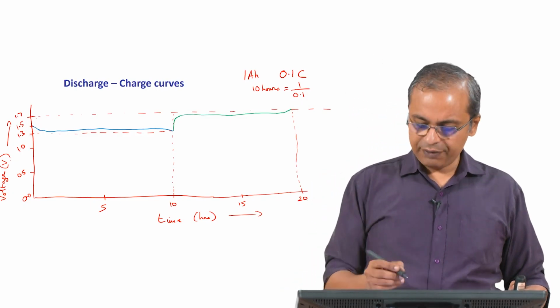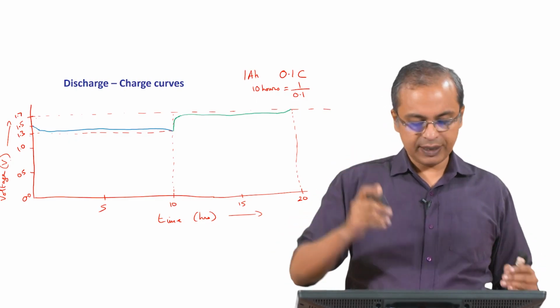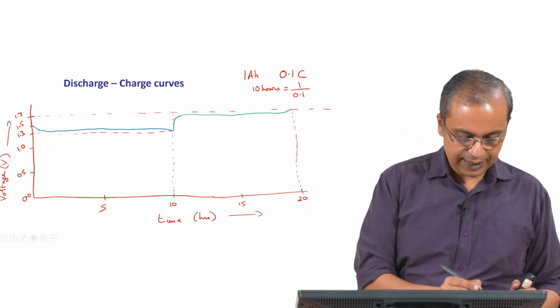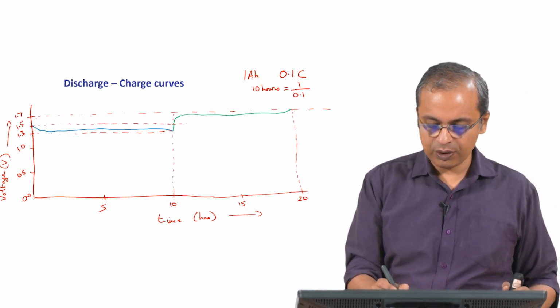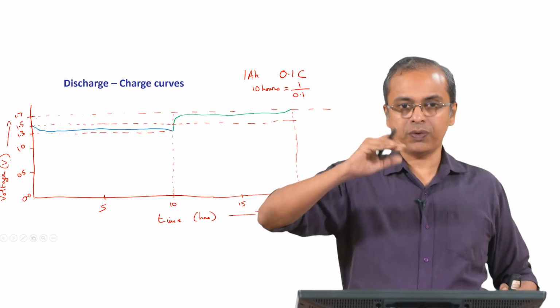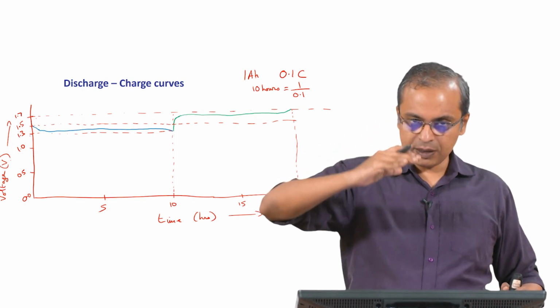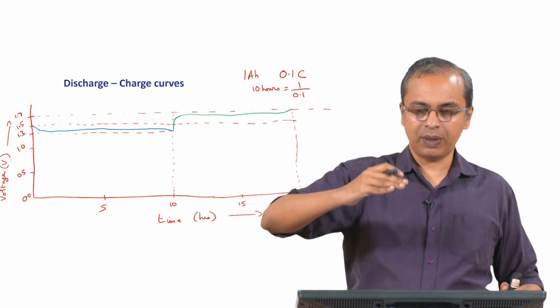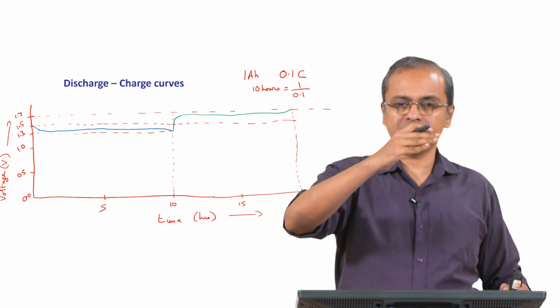So, generally by the way, if you look at this curve, I will draw a guideline here for 1.5 volt. What you will typically see is that even though you rated the battery at 1.5 volt, discharge happens at values just below the 1.5 volt, we are keeping above 1.3, say 1.4 volts.